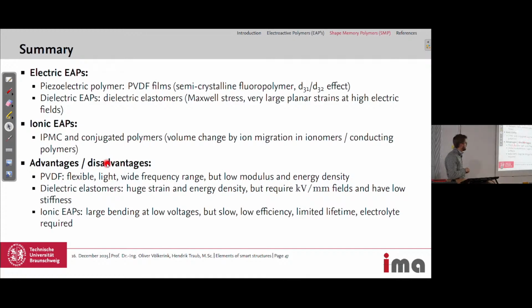If we look at advantages and disadvantages, PVDF is flexible, light, and has a wide frequency range, but low modulus and energy density. The dielectric elastomers have huge strains and also high energy densities, but require high fields and have low stiffness. So again, large displacements are possible, but only low forces.